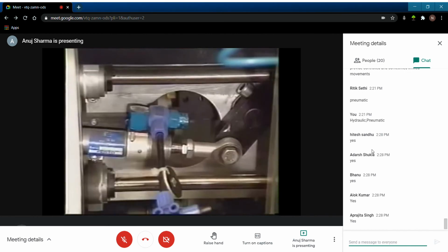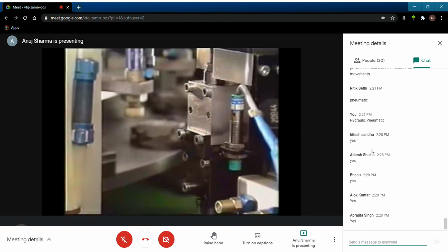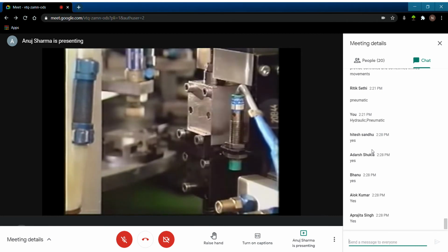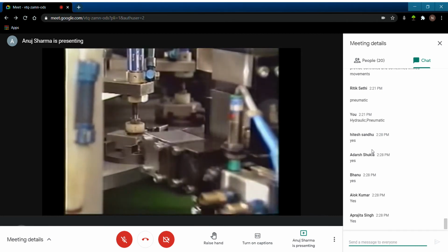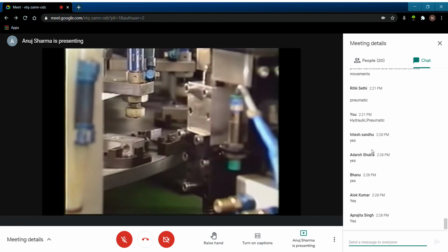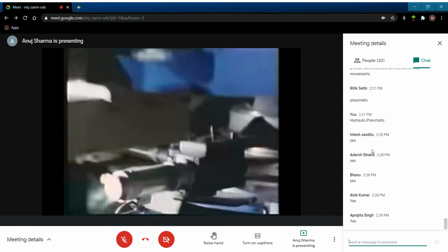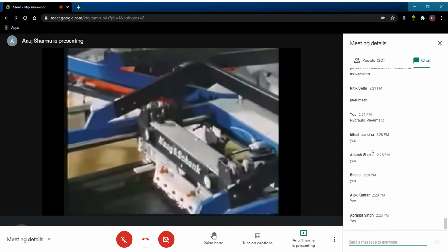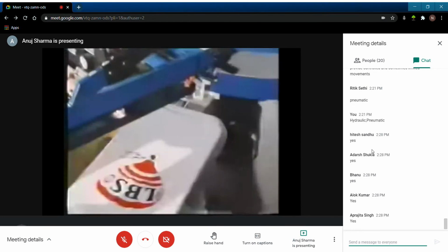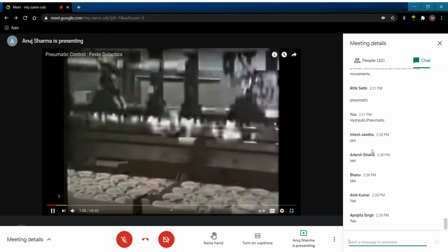Compressed air is fast. For example, short cycle times can be achieved in automated assembly applications. At the same time, it is overload safe. If the machine jams, pneumatic motors or circuit components will not burn out. Another advantage is that compressed air is clean. This is very important in the textile and food industries, where sanitary conditions are of primary importance.